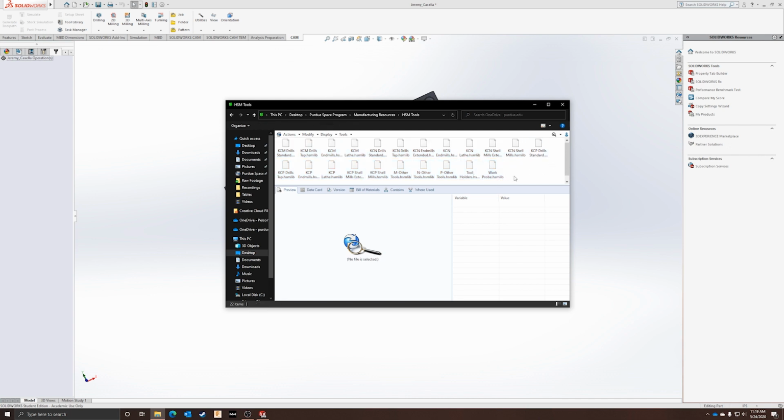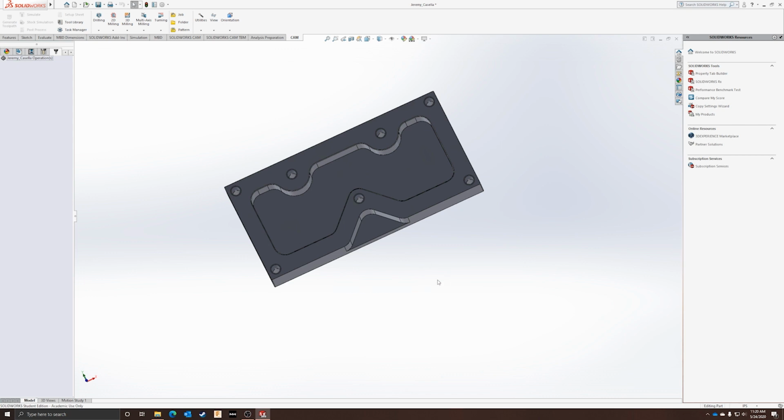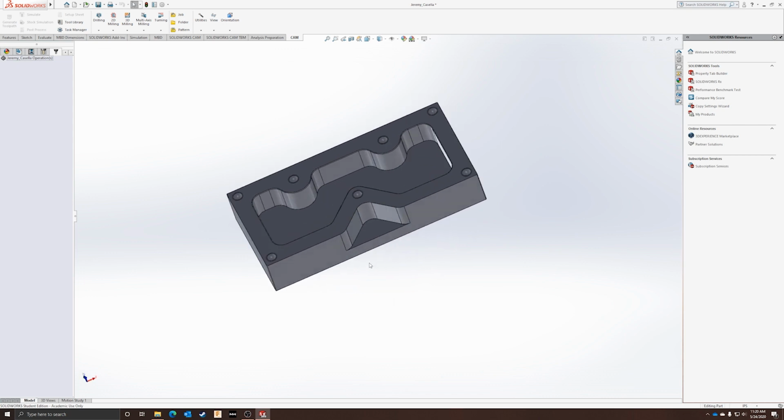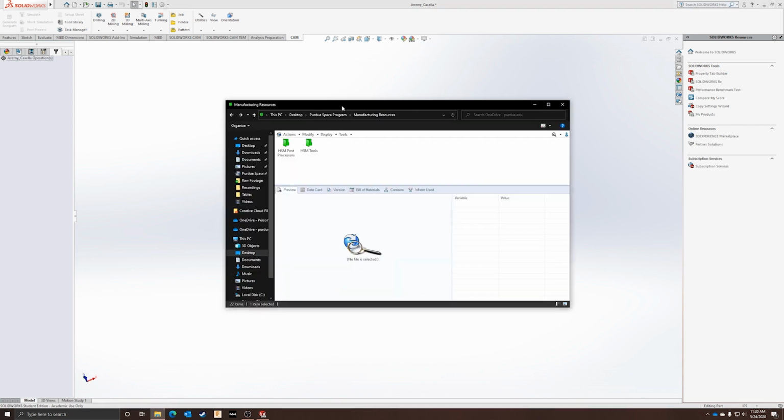So end mills, drills. N is for non-ferrous, which means aluminum, and then P is steel, and then M is for harder materials. Right now, we're probably going to be mostly doing N for non-ferrous and like end mills and lathes, etc. So to start off with, we'll be doing the setup you guys need to do. So these folders are here, and you'll also be able to open up your part that you guys worked on for training. Ideally, you did this. It's inside of the temporary training folder. If you have to copy mine, you can, but ideally you don't.